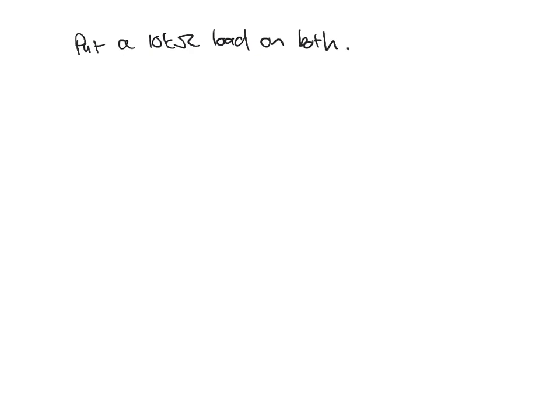So we connect our Thevenin equivalent circuit, which has a voltage source of 60 volts and a resistance of 22.33 kilo ohms, and this is node A, and we connect a 10 kilo ohm resistor,